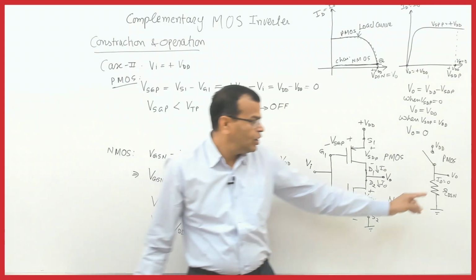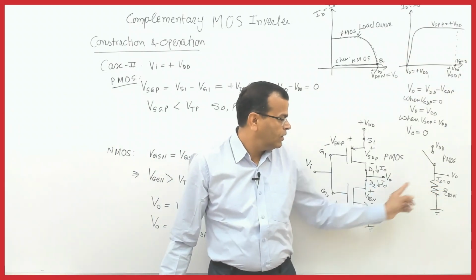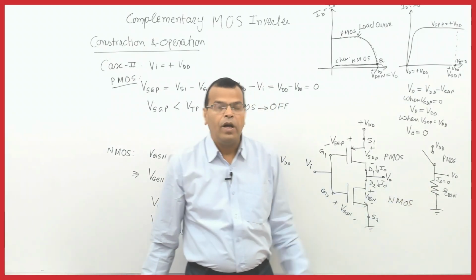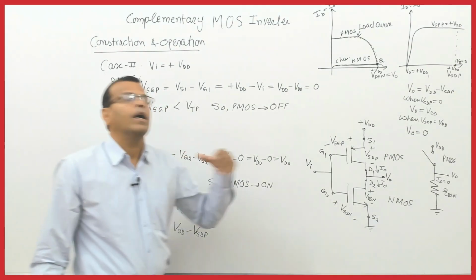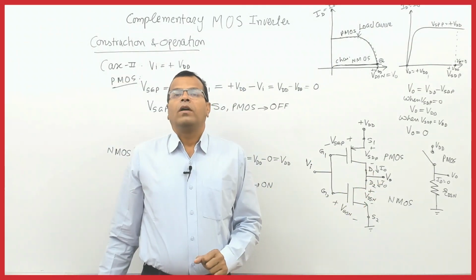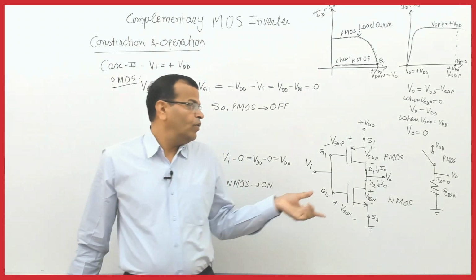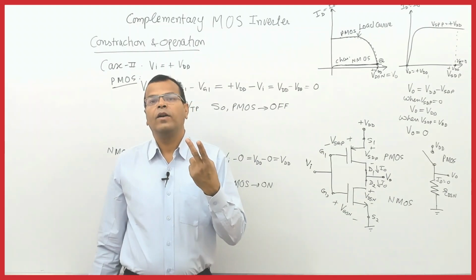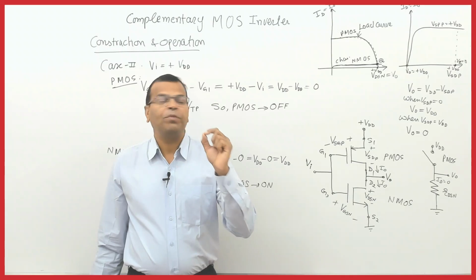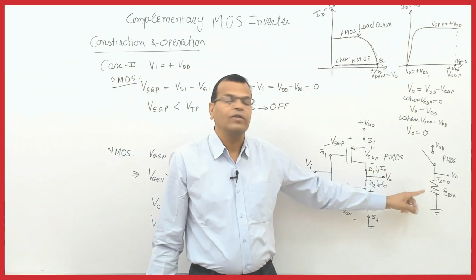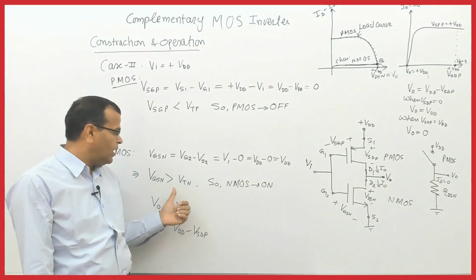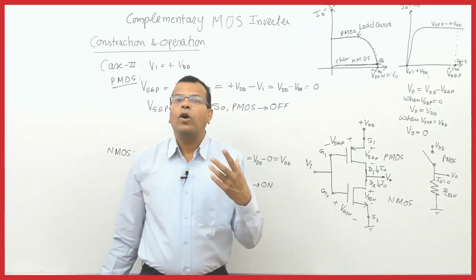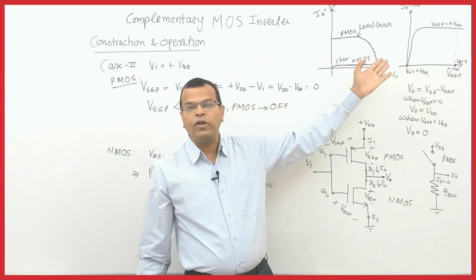And if drain current is 0, then the voltage drop across the NMOS in on condition is 0, or very small we can say. When the voltage drop across the device is very small, it works in the ohmic region of operation, offering a finite resistance. So when the gate voltage is more than the threshold voltage and the voltage across the device is small, the only region of operation is what? Ohmic region. We have discussed that part already.